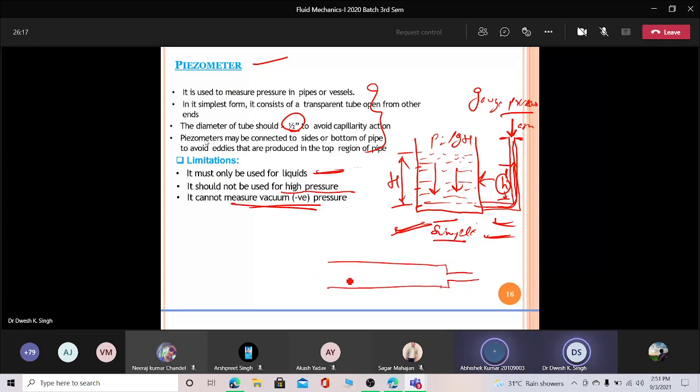So what happens here: this is a pipe system. Let us consider that this is D and this is small d, and D is greater than d. So what happens when fluid comes here? It will suddenly find a change in the diameter. So in this area in particular, I will find some eddies like this. Eddies start moving like this due to this obstacle. Fluid will come, and a sudden change in the diameter will generate some eddies.